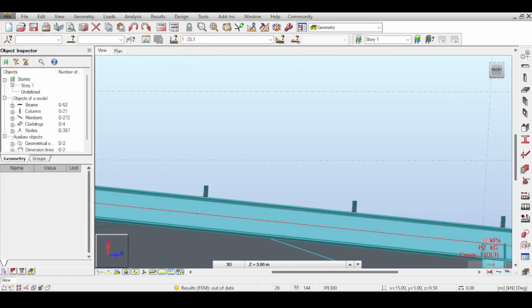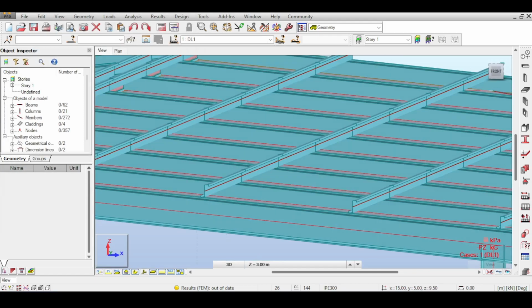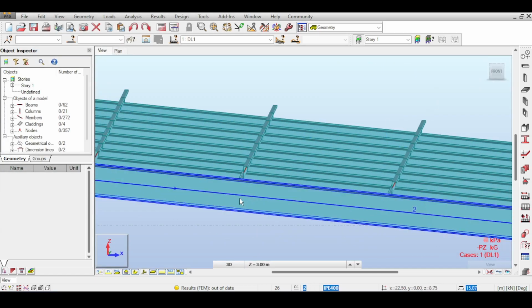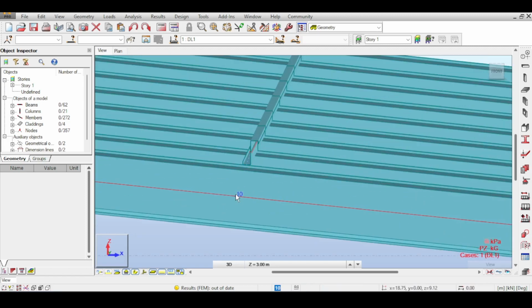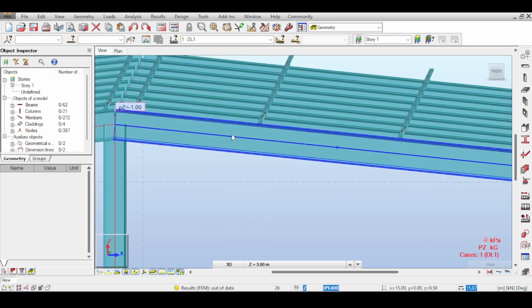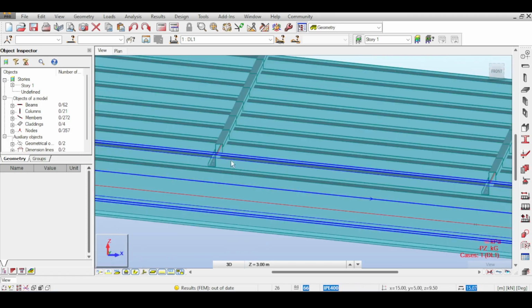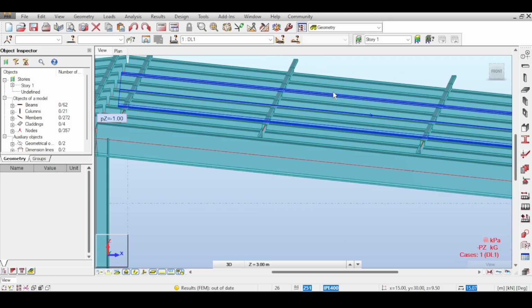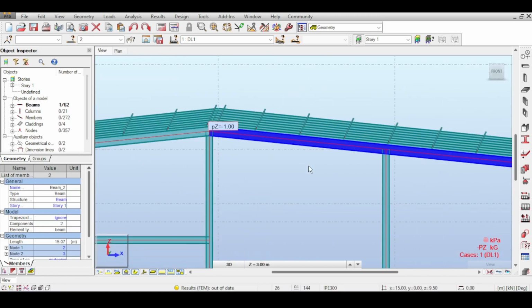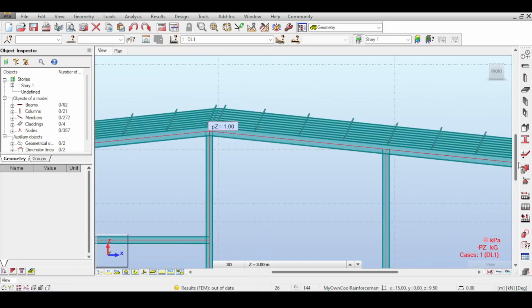So you need to keep the top side on the same elevation so that the purlins can basically do their magic. Now, if you change the section here, this will change the height of the section, which means you need to pay extra attention in detailing to push the columns a little bit higher so that the sections still remain with top side in the same plane of the other portal frames. Or you could just not do that and get the best of both worlds, because I told you there are two options.